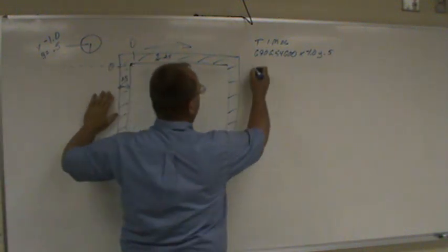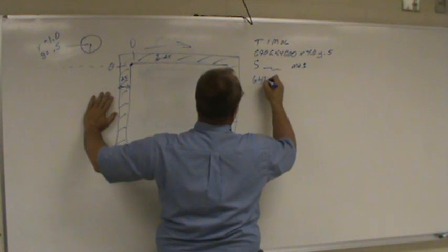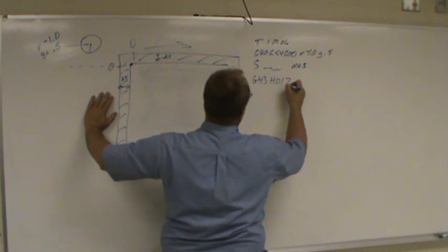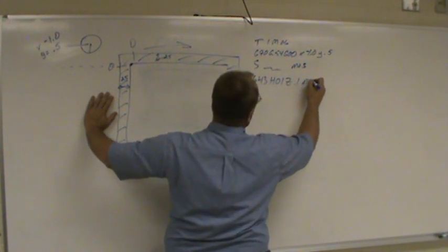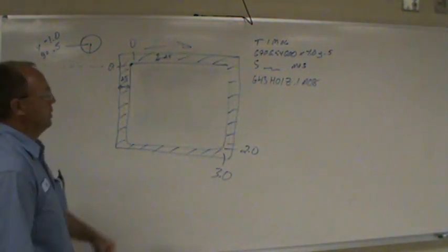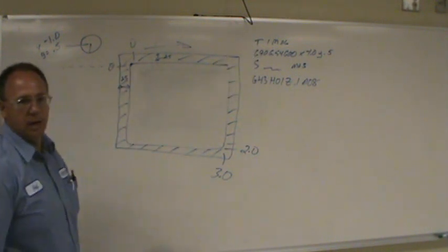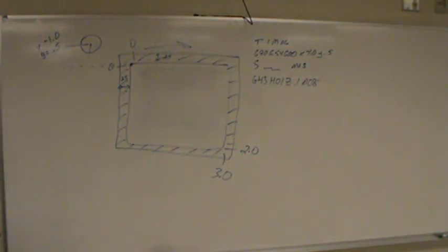And then you'd have your S, M03, G43, H01, Z.1, and if you're turning your coolant on, M08. Notice the same four lines, pretty much the same information, as we've been using. So we have our start point.